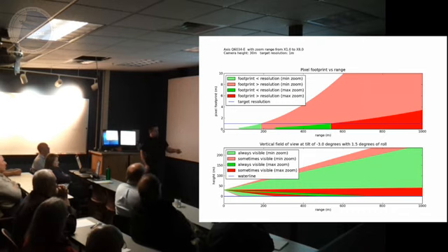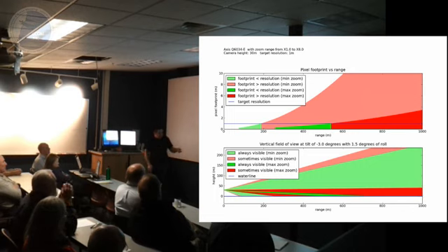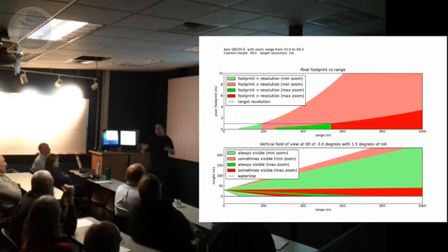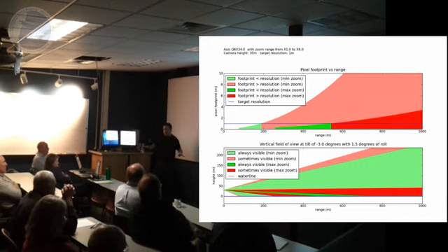So now this is just to get our footprint up here. If we imagine this is the ship right here, our camera is looking out at the side, and again there are 2 ranges. There's the lighter range, which is when we're zoomed in at 1, and the darker red and green when we're zoomed in at 8. If the camera is looking down 3 degrees, where is that field of view? Now, the reason there's a red and green area is that if you're on a ship, there is going to be some motion. In the ice, it's not like there's any sea state, but as you're going through the ice, the ship is going to move a little bit, and sometimes the balance of the water tanks and such will make the ship move.